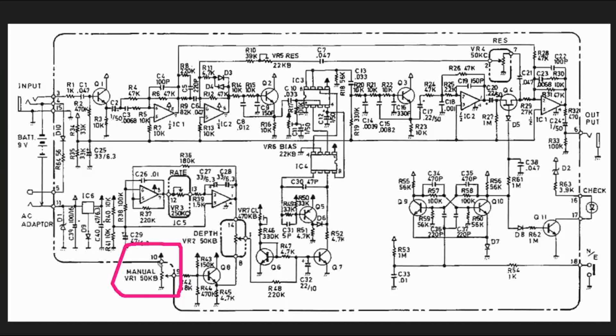So if you see that we have a voltage divider from our plus 9 volt supply here, as we put more voltage on the base here, then this resistance between collector and emitter drops. And when that resistance drops, that means we're going to have a DC voltage present here.